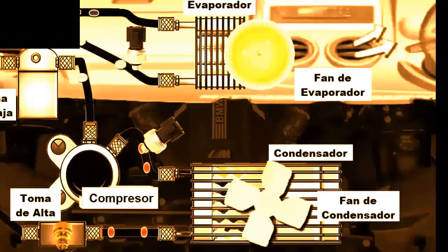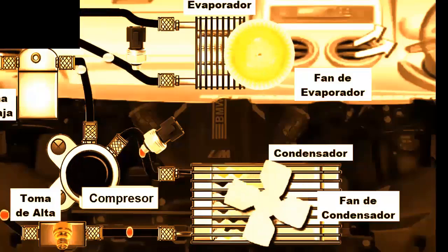Now let's look at the diagnosis of the pressure sensor. A. Before replacing the sensor, it's essential to check its voltages, signals, and wires to ensure that the fault does not persist after replacement. This will ensure an effective and accurate repair of the air conditioning system.